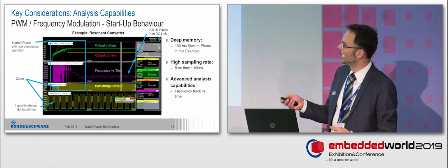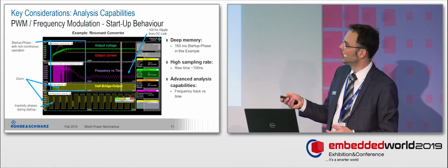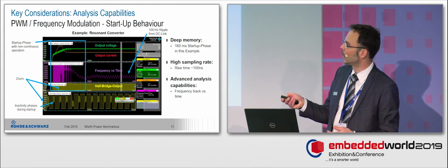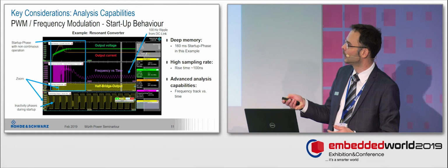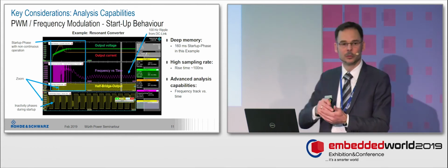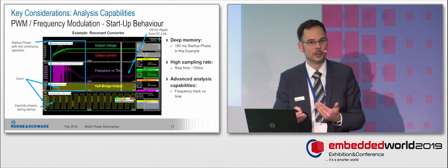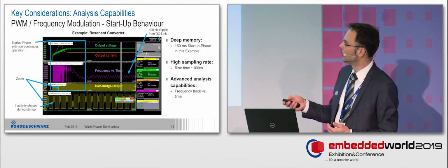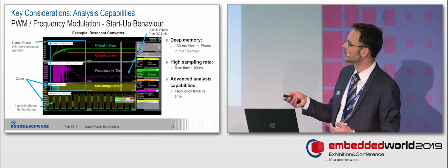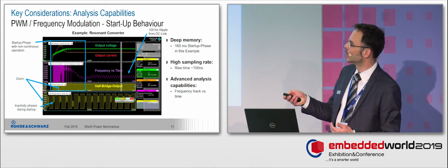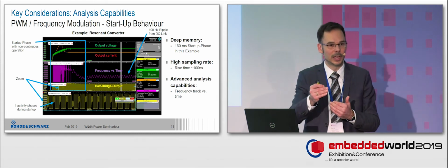And you can see in the beginning the frequency is not stable. You would find here a frequency maybe in that range sometimes when the switching is working, and then you find this kind of ringing which goes out of the screen because it's a totally different frequency. And then at one point in time it stabilizes, and you see the resonant converter usually starts at a little bit higher frequency.